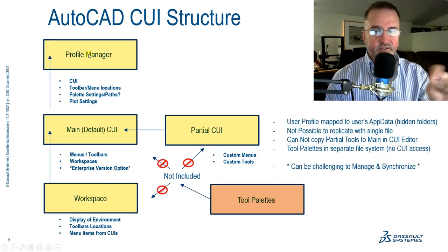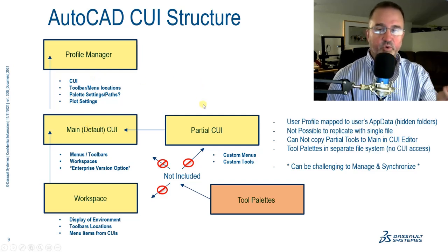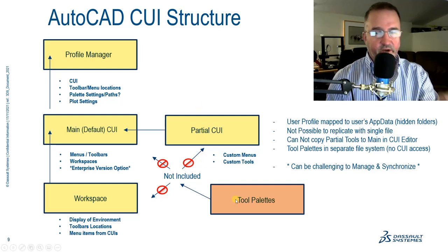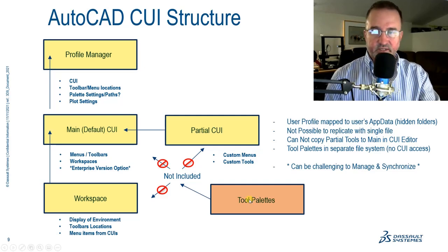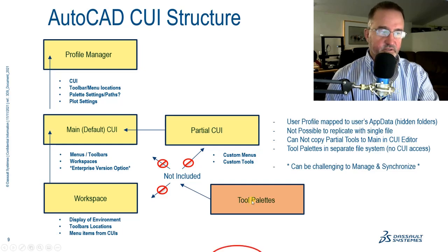And the profile doesn't contain the workspace, but it does contain the main CUI. It gets to be really confusing. It can be a real challenge to synchronize these things. And I think the other thing that I want to point out here is that tool palettes, which tend to be the area that most people customize, especially CAD managers, are not part of the CUI system at all. It's a completely independent system.